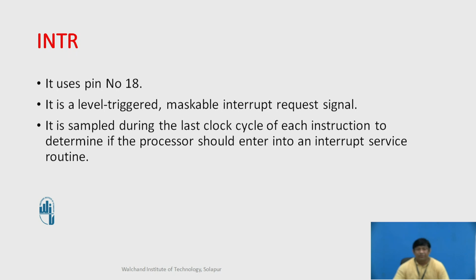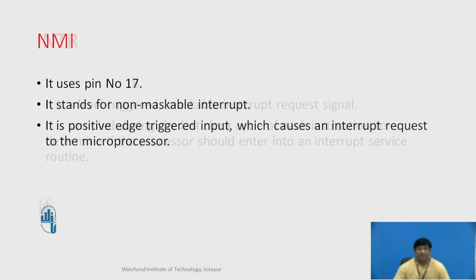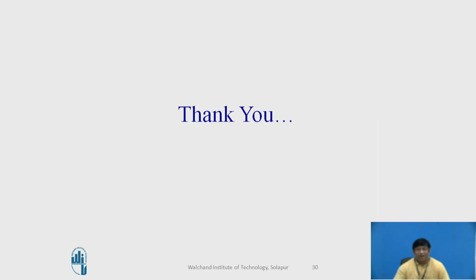INTR uses pin number 18, that is an interrupt request. It is a level triggered maskable interrupt request signal. Then NMI, that is nothing but a non-maskable interrupt. It is a positive edge triggered input which causes an interrupt request to the microprocessor.